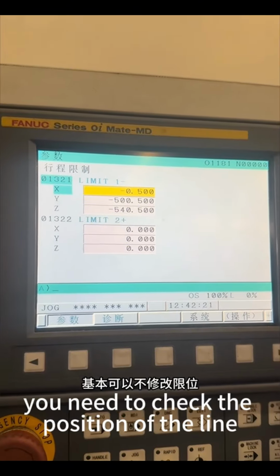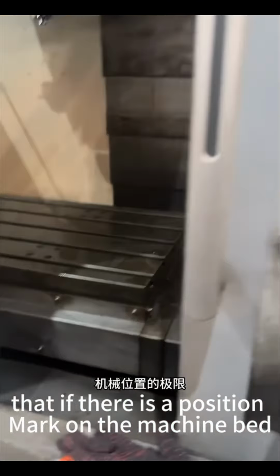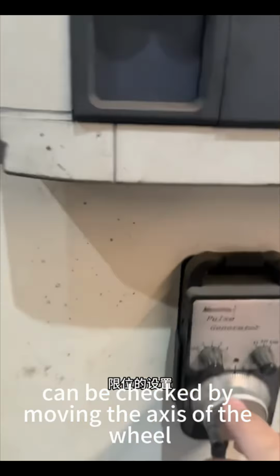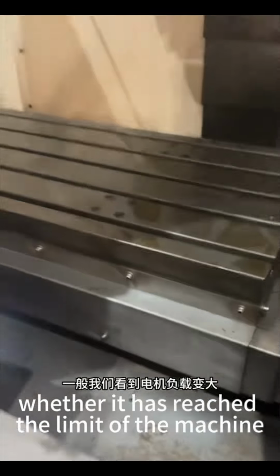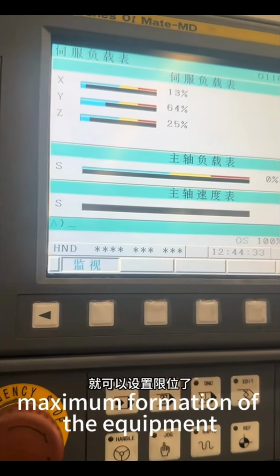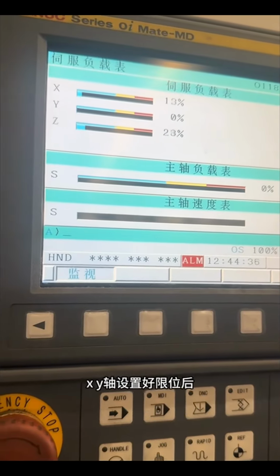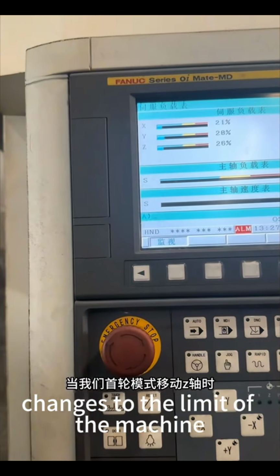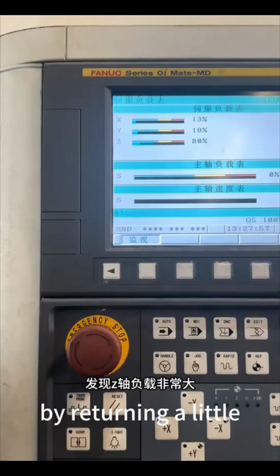After changing the origin, you need to check the position of the limit. If there is a position mark on the machine bed, you can basically leave the position unmodified after setting the origin. The machine limit can be checked by moving the axis with the handwheel and checking the load to confirm whether it has reached the limit of the machine. The limit setting must ensure the maximum stroke of the equipment. Generally, when we see the motor load rise at the machine limit, we return a little and set the limit position.